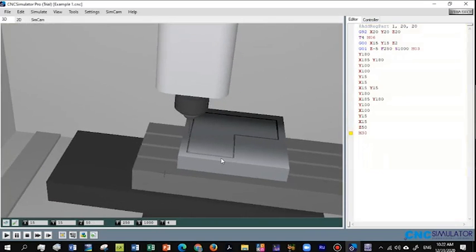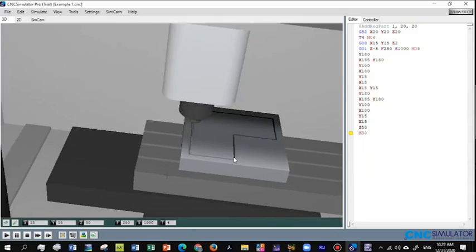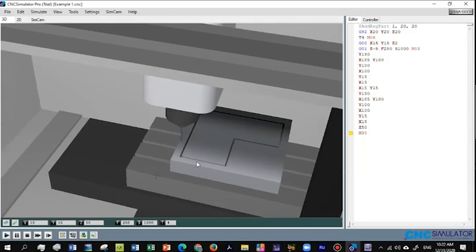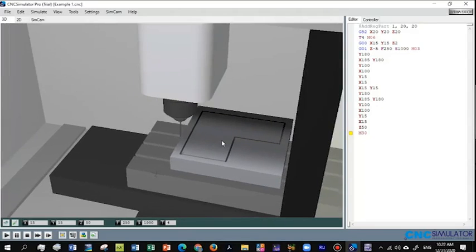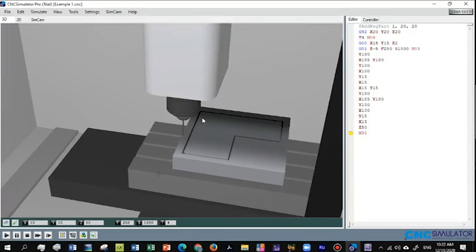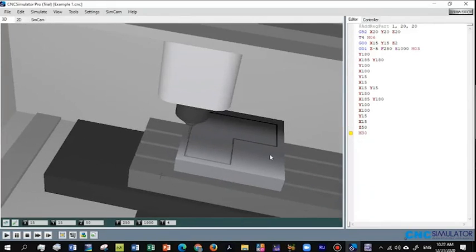As I told you, some of the coordinates in the example that we have in the slide are more applicable to real machines. So if you try to use the code directly, you cannot generate the exact shape here. But what you need to do is redefine the workpiece dimension here, and also the size or the coordinate for your shape based on the given drawings, for example.